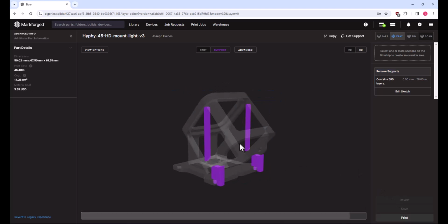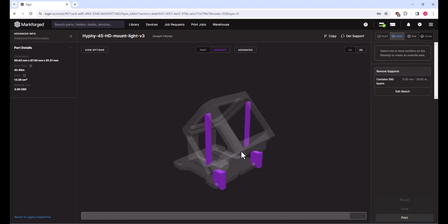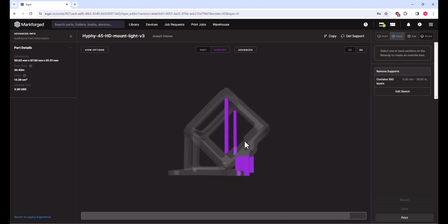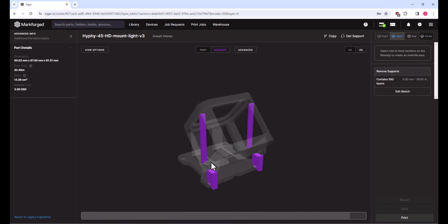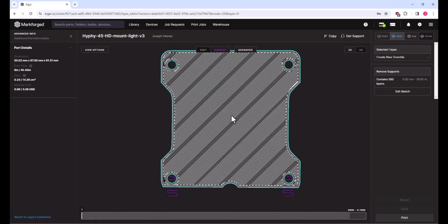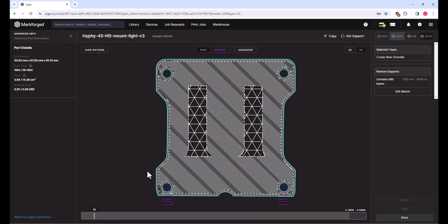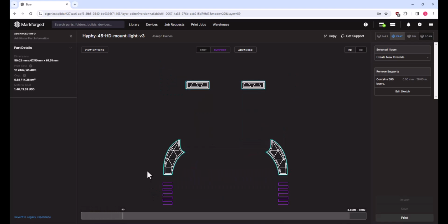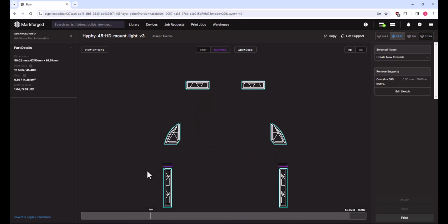Awesome. Okay, so I just need to probably add a little bit of support blocker right in this region. It's just where that rectangle didn't hit. So let's go ahead and do that. Go back into 2D mode, and this time I can start the support blocker higher up. Okay, so it's generating right in here.